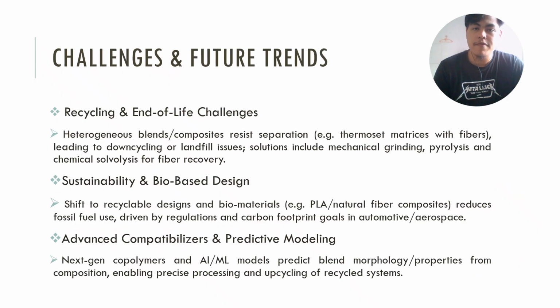Despite all of development in this, there are challenges and future trends. The first one is recycling and end-of-life challenges. Heterogeneous blends and composite resist separation, for example thermoset matrices with fiber, which leads to downcycling or landfill issues. Solution includes mechanical grinding, pyrolysis, and chemical solvolysis for fiber recovery.